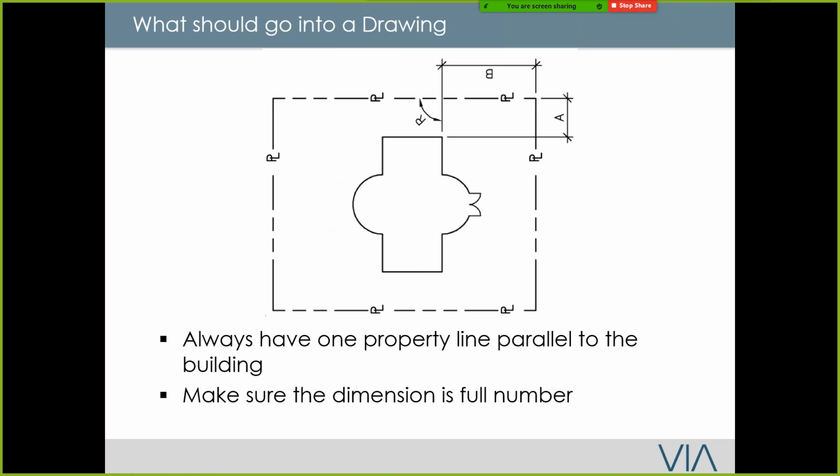All right, property line. If you're doing any building, you always have to create some sort of key plan to show the contractor where you're going to start your building. Here, it's basically dimensioning to the corner of the property line. So I always say start with any corner, one of these 4 corners, and dimension it.